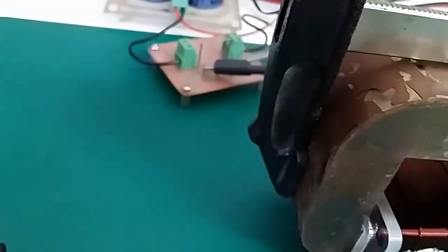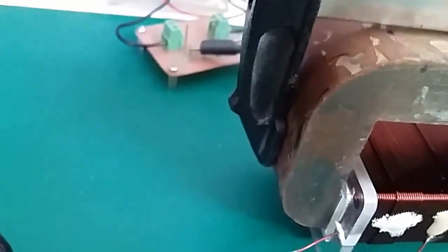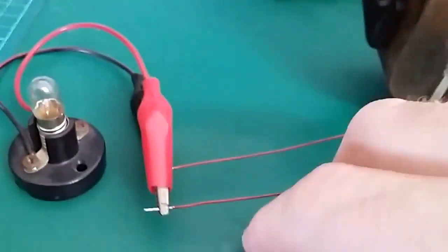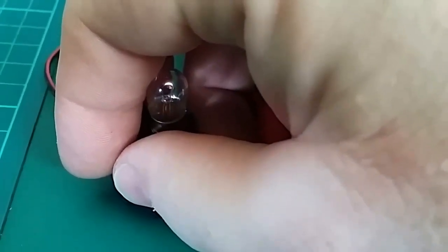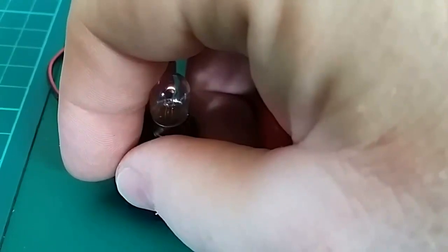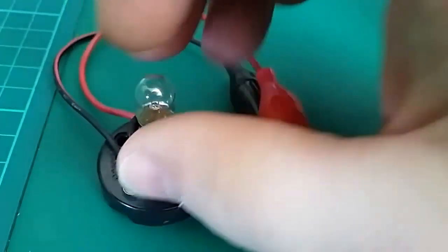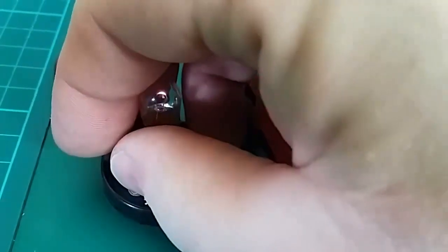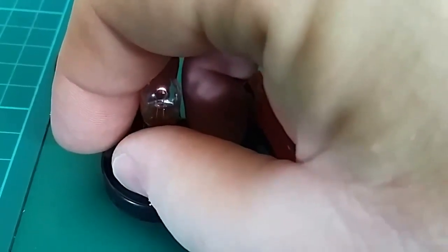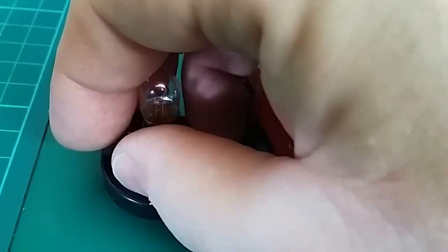I should explain why, because some people may not actually realize. Remembering what I said, it's the change in current, which effectively is the change in magnetic field, that creates a voltage. So the voltage that we're seeing over this globe at the moment is a time weighted average of the entire current that's in the system.